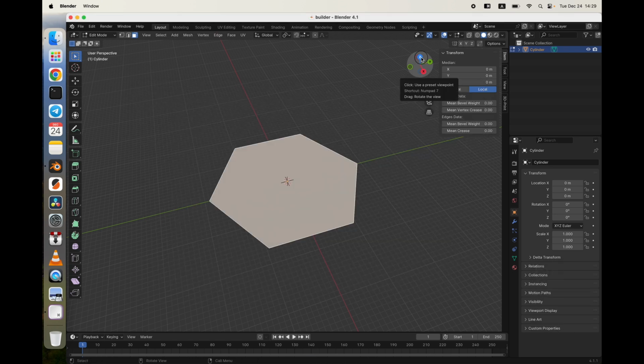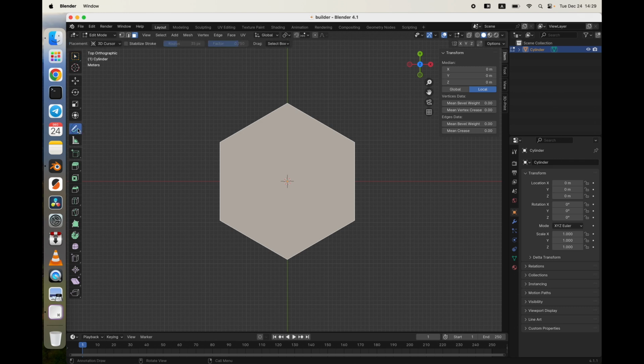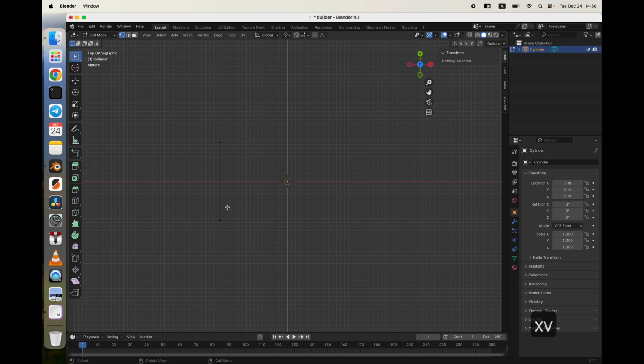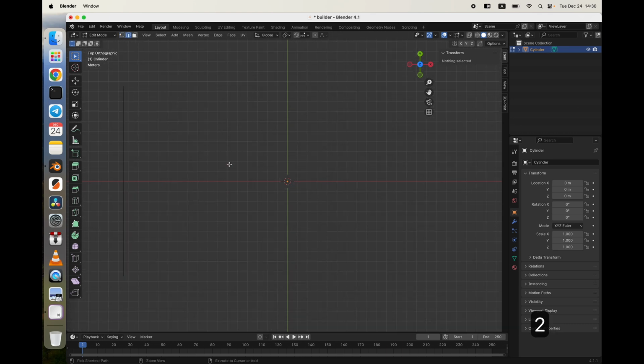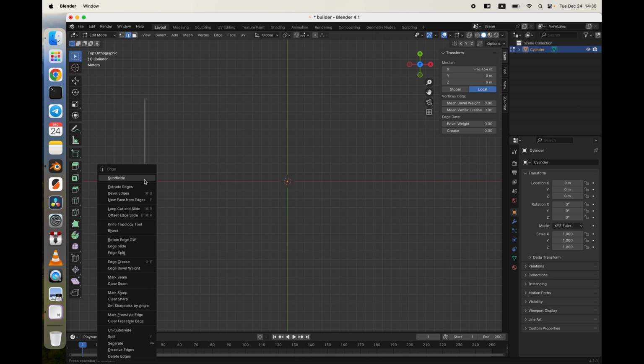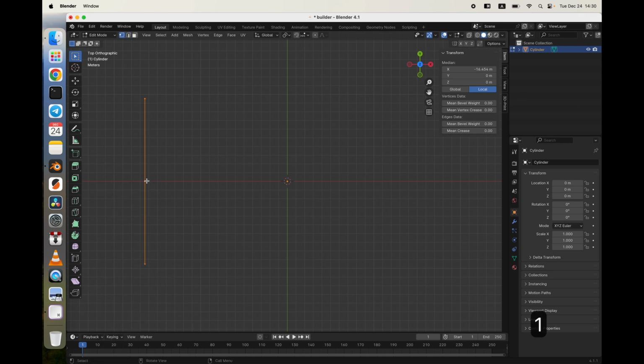Click here on that icon for top-down view, and I will show what we want to do. We want to make a key here, and a gap here, like a puzzle, to make our tiles self-locking. Let's undo that. And I will select another instrument. Press 1 for vertices editing, select all these vertices, X and V to delete them, we need only this edge. 2 for edges editing, and we will subdivide this edge, OK, 1 for vertices editing, and we will bring it to 3.